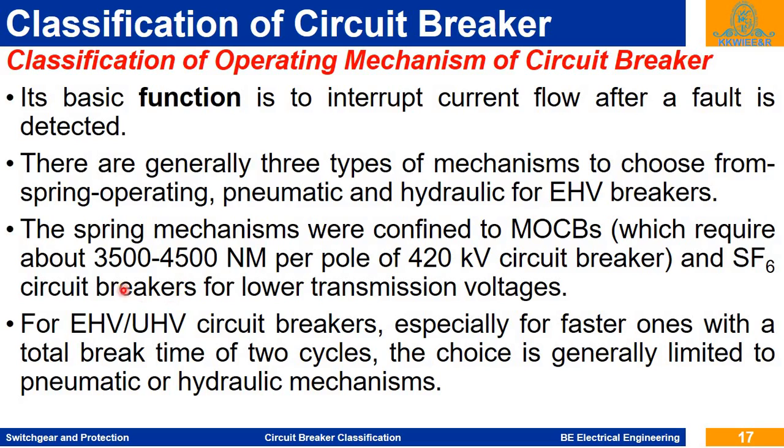During this we require a high torque to pull the moving contact or to close the moving contact, so that when the contact closes, there should not be a loose connection. So we have to apply high force or torque, and it should be maintained in the closed condition. Again, while opening the contact, we require high torque. So for that purpose, spring operating mechanisms, pneumatic and hydraulic mechanisms are used for the extra high voltage circuit breakers.